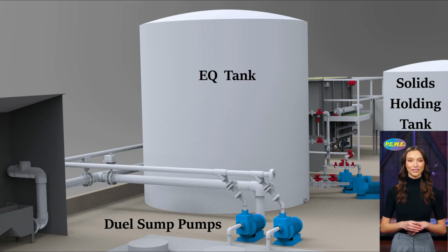basin. Within this tank, the pH control system automatically adjusts the wastewater to the desired set point by dosing acid or caustic based on real-time feedback from a pH probe. As the mix pump circulates the water, the chemicals are rapidly dispersed, allowing the entire tank volume to reach a consistent and stable pH.